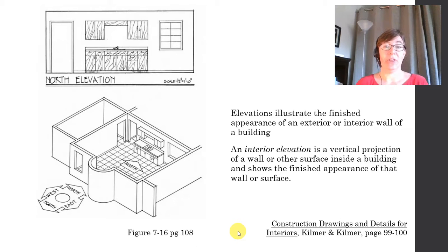So the point of an elevation is to illustrate the finished appearance of an exterior or an interior wall of a building. Now you're in an interior design program, so you are most interested in and focused on the interior of a room. And so today we're going to talk specifically about interior elevations. An interior elevation is a vertical projection of a wall or other surface, if you happen to have something else, inside of a building. It's going to show the finished appearance of that wall or surface.